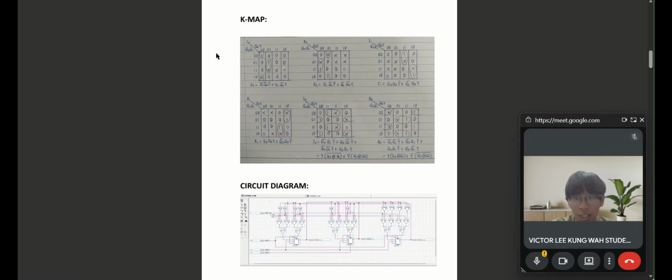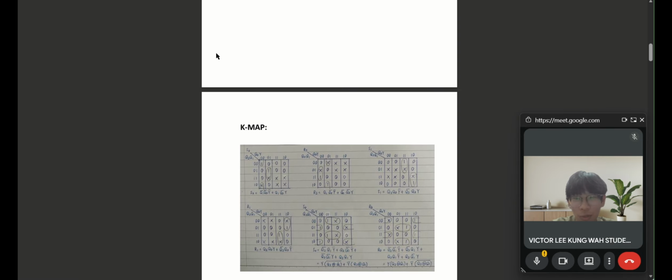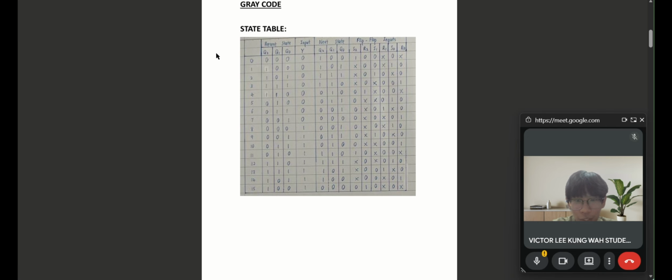equation. The circuit is a 3-bit sequential logic circuit constructed using 3 SR flip-flops that share a common clock signal. The outputs of the flip-flops are labeled Q2, Q1, and Q0, which together form a 3-bit output. The clear and preset inputs are used for initialization. When clear is activated, all flip-flop outputs are reset to 0. When preset is activated, the flip-flop outputs are preset to 1.